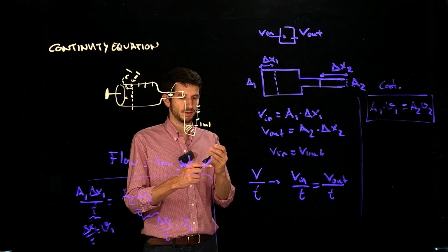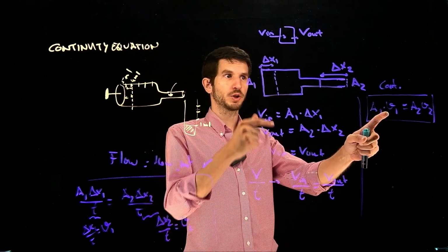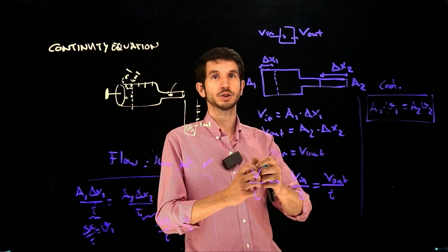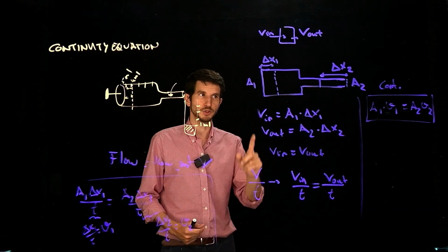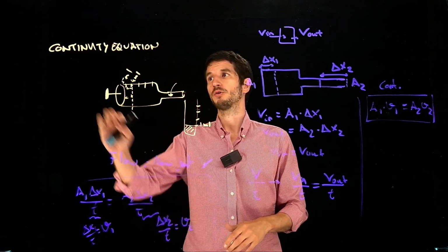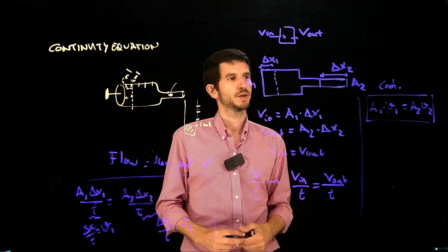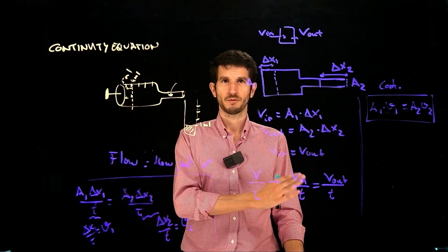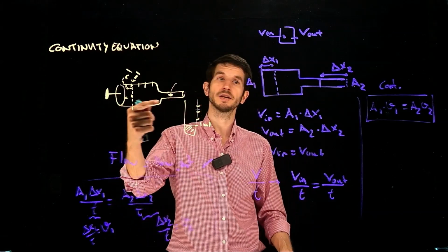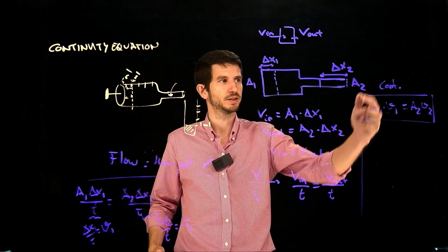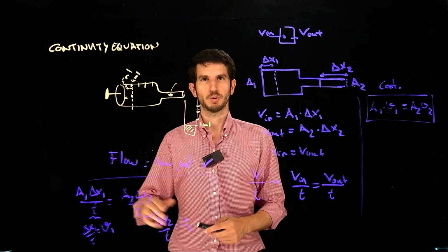And it's an interesting thing. The larger the cross-section, the slower the fluid is going to be flowing. The smaller the cross-section, the faster the fluid is going to be flowing. This is the first principle, the principle of the continuity equation, which follows from incompressibility of fluids and also conservation of matter, if you wish, right? So the first idea in here is flow of volume. How much push is how much gets out. How fast it goes in needs to be how fast it goes out. From that, we extract this equation, which is going to be very important to study Bernoulli's principle.